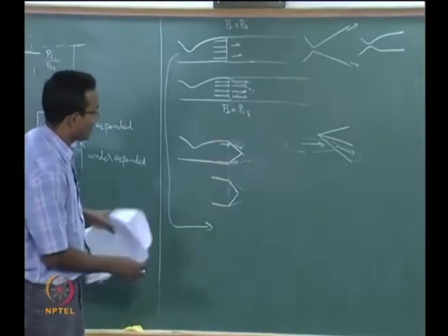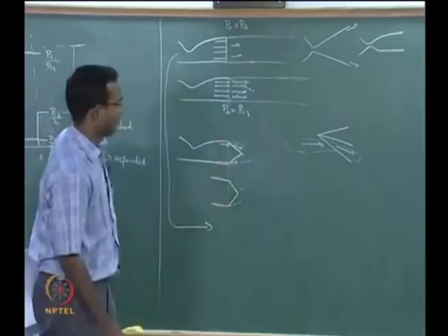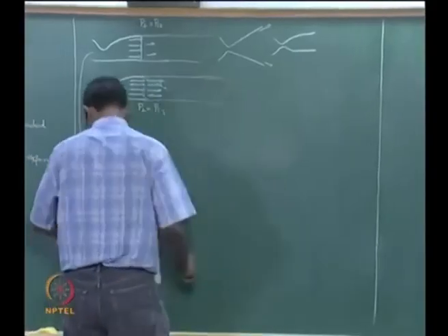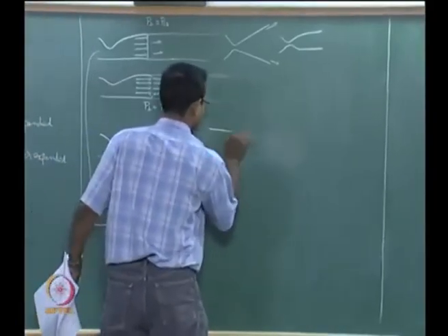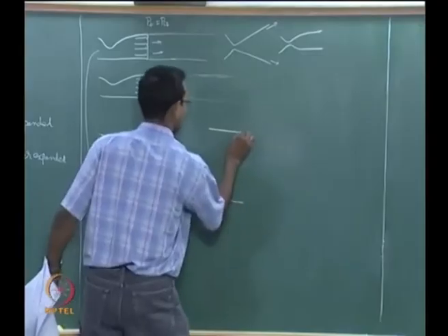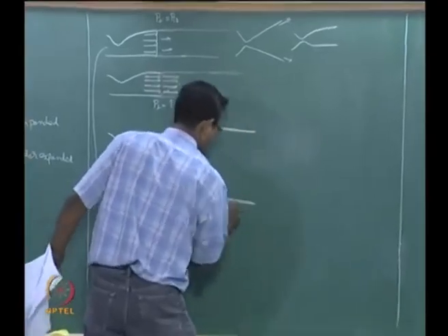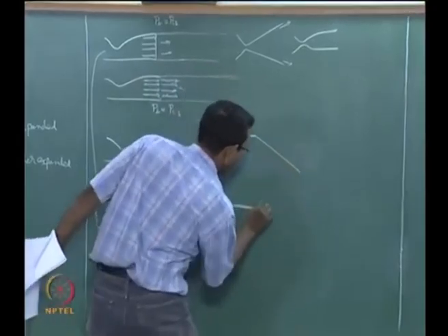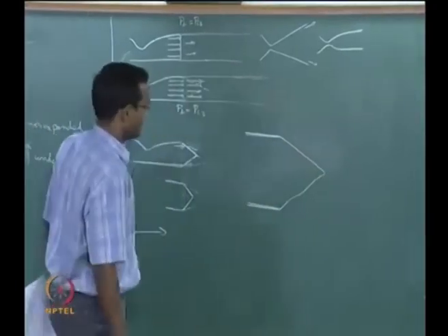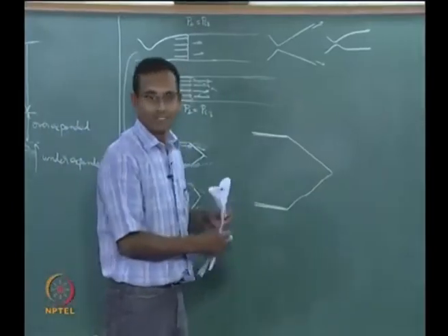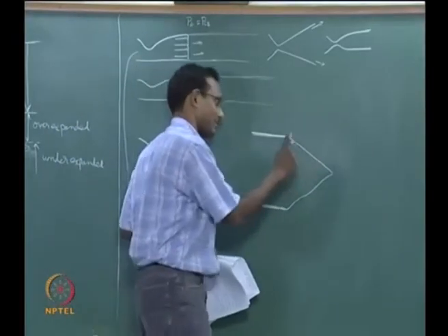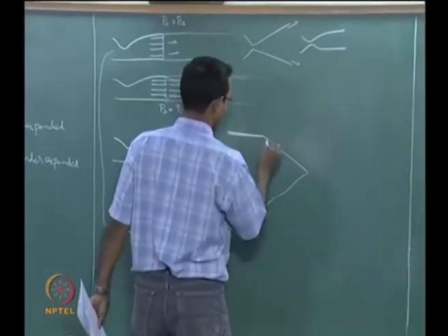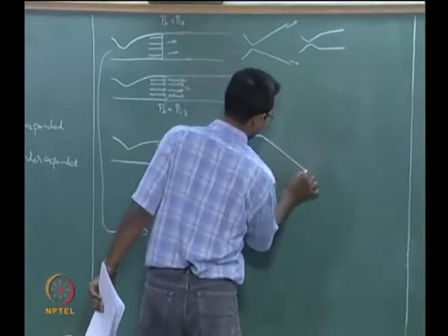We will look at what happens in this region, we will draw a much bigger picture now. This is my full nozzle, and I am having an oblique shock from both sides. I just wanted to draw it slightly wavy, okay, so that you remember that this is a shock. Ideally you should just draw straight lines because in real life it is a straight line. When you see pictures from experiments, it will be a straight line really.